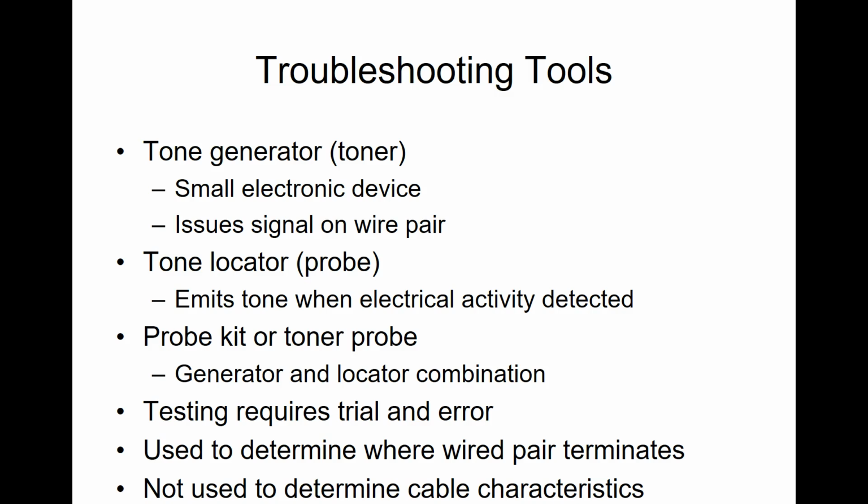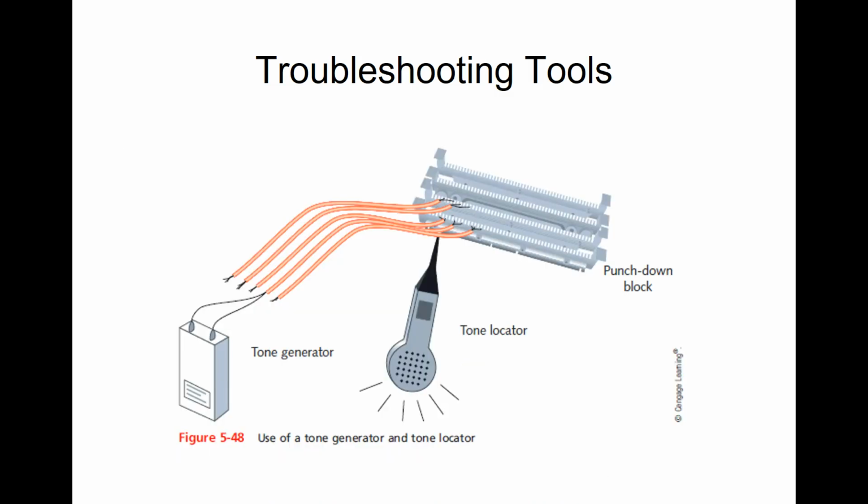So we're actually going to be live in here and play with a couple of these tools. Some of these tools you may have seen phone companies use, and I'm going to bring in one so you can see. So we create a tone generator and we locate cables this way. If you've been around when they're putting in phone installs, that's a pretty common thing for an electrical service. You might also see them called a fox and hound.